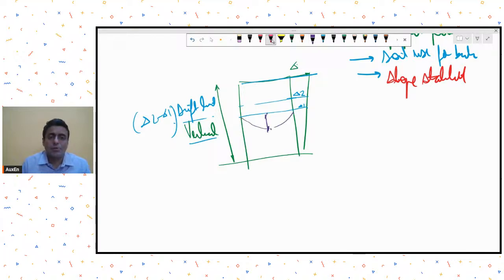Oh, sorry, these are not vertical deflection limits. Wait a minute. These are horizontal deflection limits. Similarly, there will be some vertical deflection limits. These are usually for elements like beams or slabs, etc. These are more to do with gravity loads.